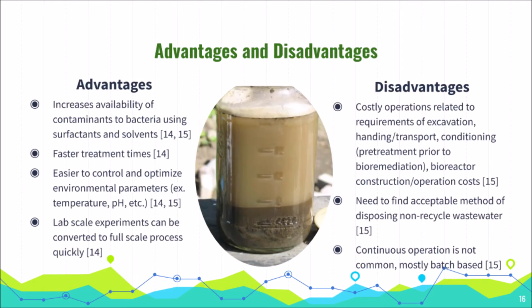The advantage of this method is that when we use surfactants and solvents, we increase the availability of the contaminant to the bacteria, which will allow for faster treatment times. Since this is an ex situ technology, it is very easy to control and optimize any environmental parameters like temperature or pH. Any lab scale experiments that were done can also be quickly converted to full-scale processes for commercial and